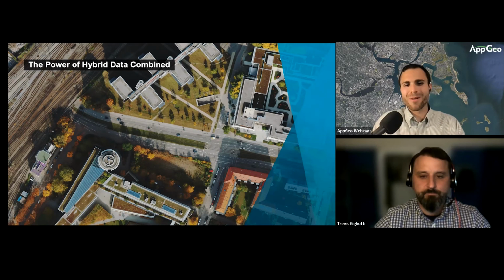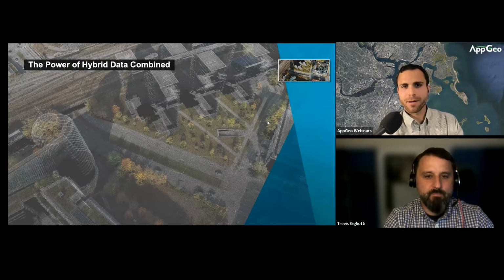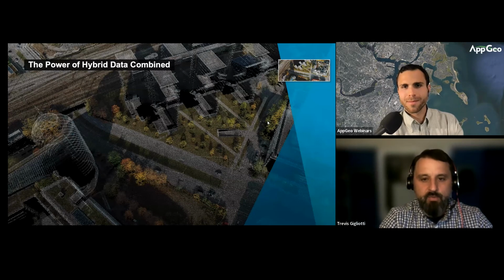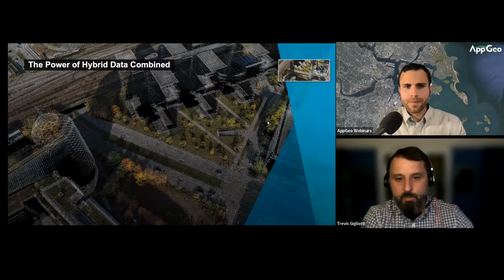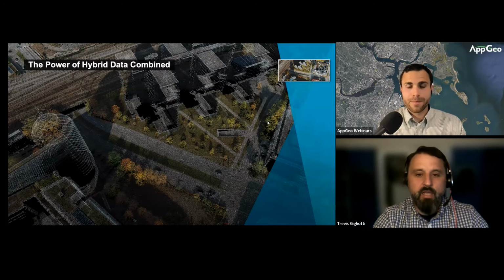Yeah, 5 centimeter imagery alone is pretty exciting, but let's see what else we've got coming up out of the box here. What we see here is the LiDAR point cloud that comes out of the MetroHD process. Because we're collecting it concurrently with imagery, we're able to spectrally encode those points with either RGB information or CIR information, which makes data interpretation a little bit easier to the untrained or even the trained eye when you're taking a look at this data set.